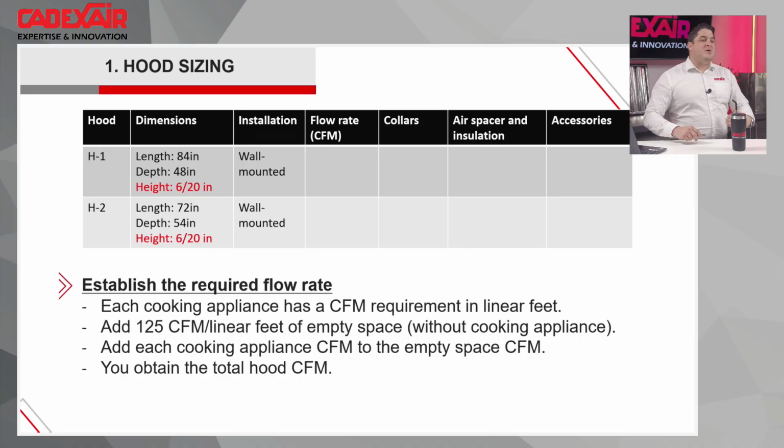And I will say nobody likes to have problems. After that, you may need to change the motor, or change the sheave, the pulley on the fan. So there's more work and involvement to make it happen. So we prefer to be in a zone where we'll be safe and we are sure the system will work.